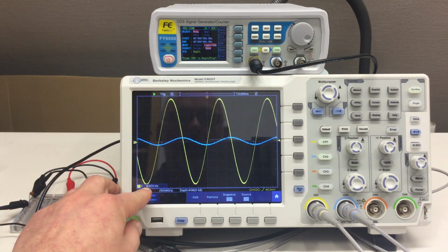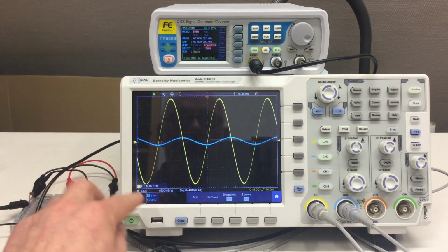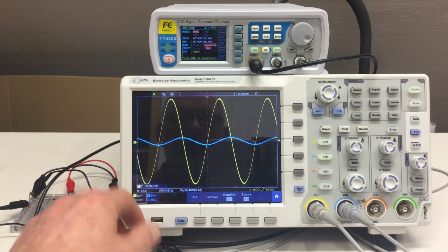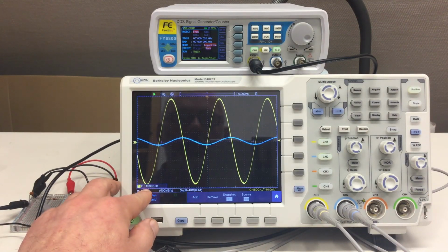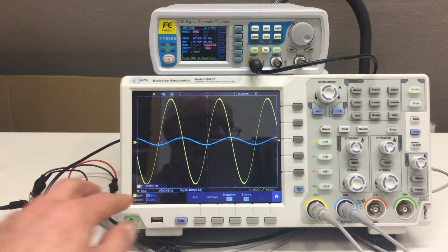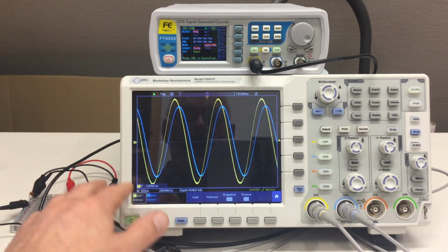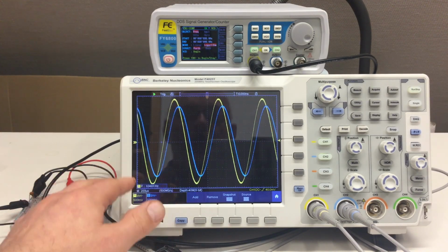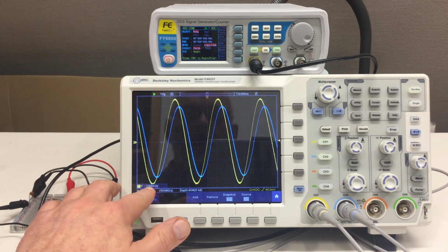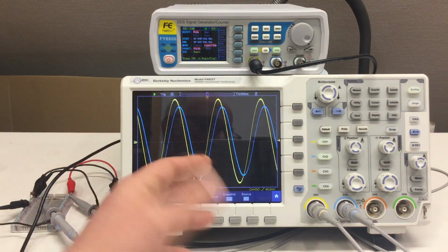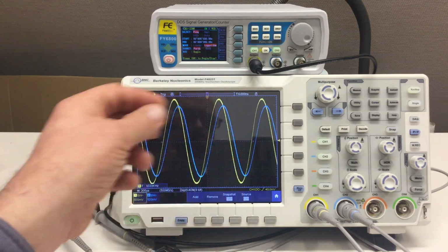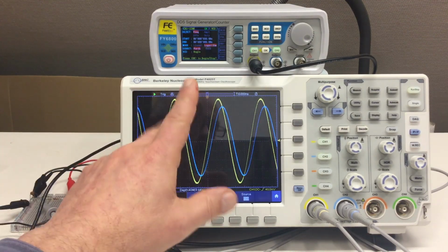Now if I go backwards from the highest frequency to the lowest at 0 volt, I start at about 19 kilohertz. And if I go from the lowest frequency up, I start at 1 kilohertz. So the VCO input is not very accurate.